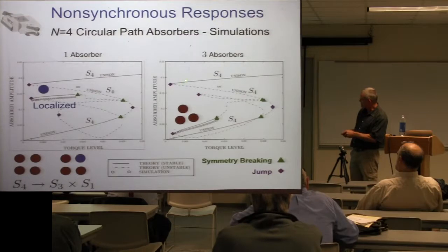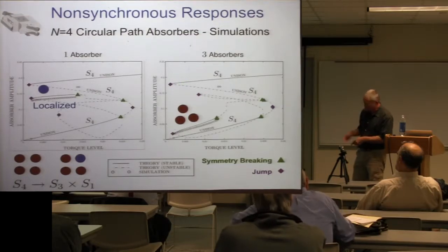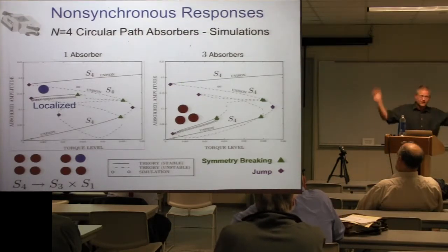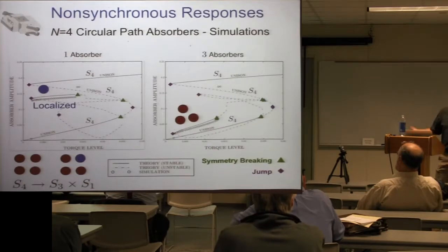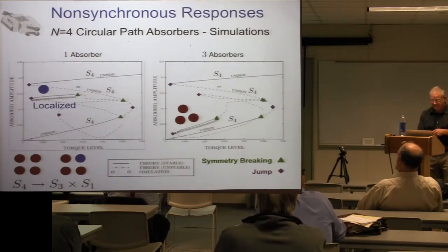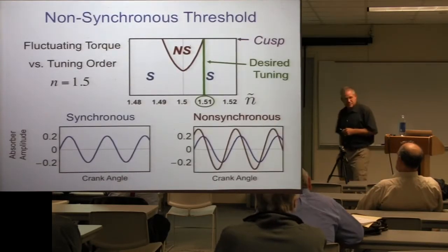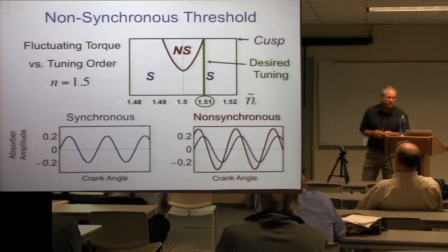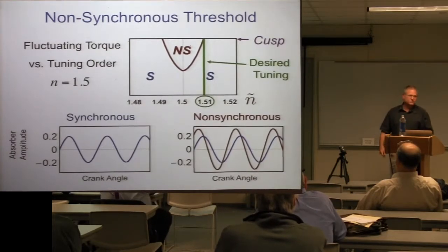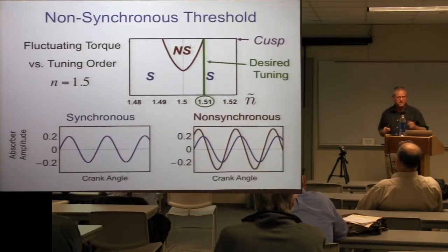decreasing vibrations, one that's amplifying, plus you have S3 cross S1 and S2 cross. You have all this nightmare and all the permutations involved of these absorber dynamics. And they're seen in experiments and in simulations. How does one get on that disconnected range? Initial conditions. So going over, you bump the system and it could go to any one. In fact, in a perfectly symmetric system, of course, there's all kinds of permutations of those.